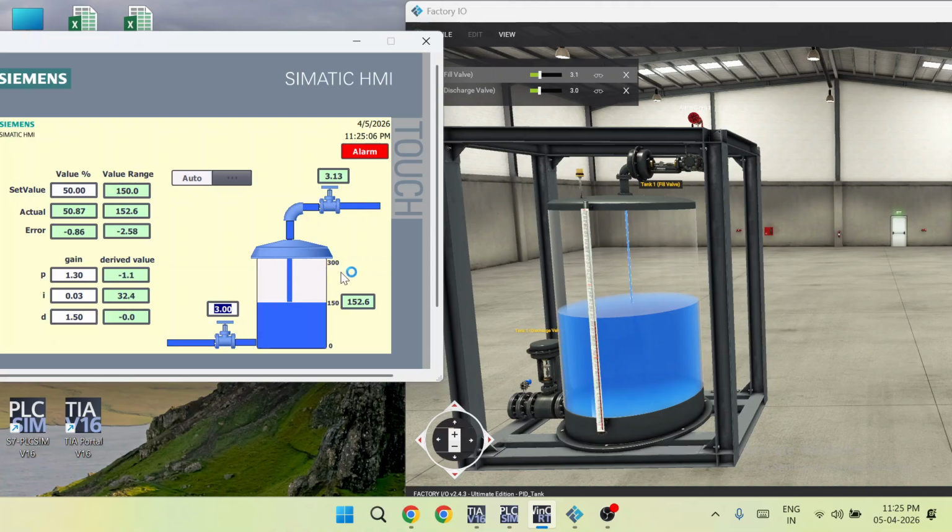So the PID after a few seconds will detect that the valve is off. And if the valve is open for some reason and not in control mode, so it's in saturation mode, continuously giving water, in that condition also the PID will detect the valve is saturated. So let's step by step check all the alarms and work of the PID.